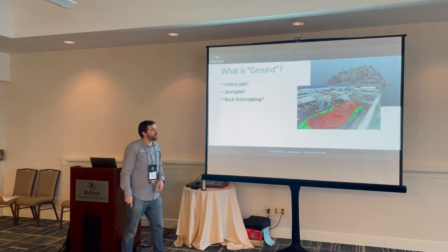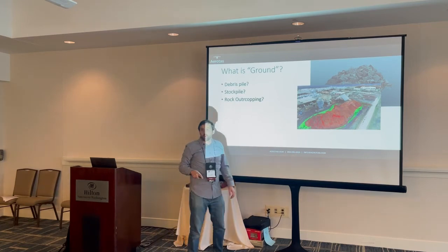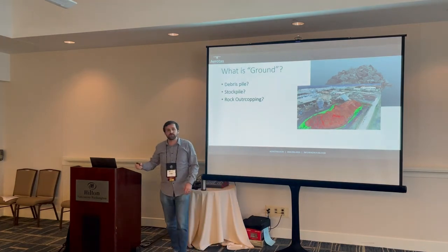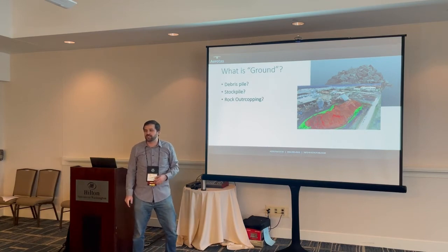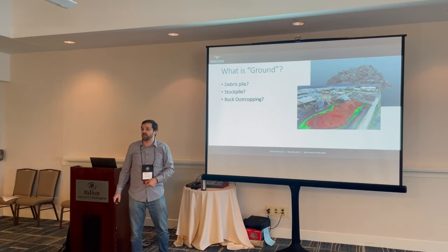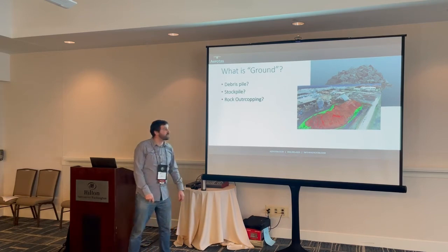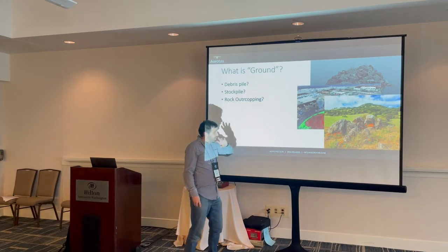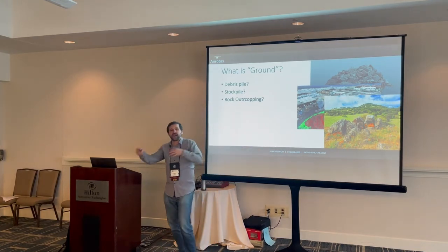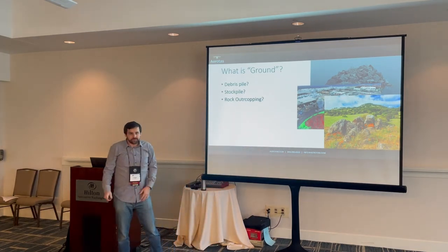Same thing with a stockpile. Is the stockpile itself ground, or is that going to be a separate object and you care about the ground underneath and then you measure the volume of the stockpile as its own different classification? Once again, that's a judgment call. It really depends on the type of survey that you're doing. Same thing with rock outcroppings: is that an object or is that actually part of the ground?